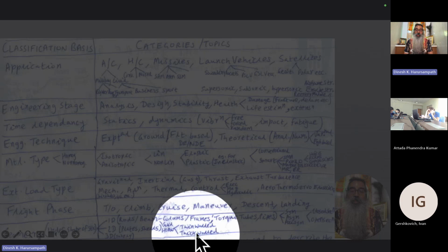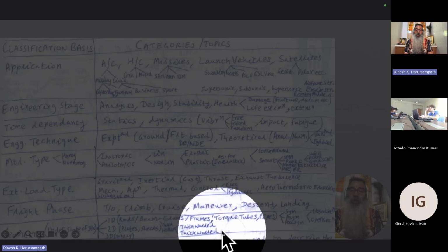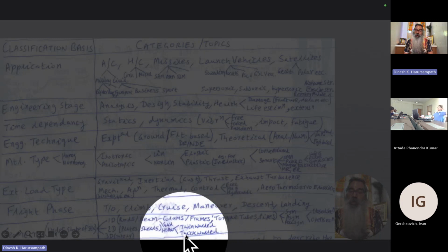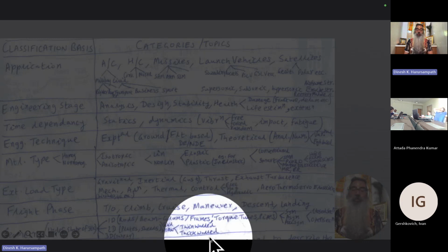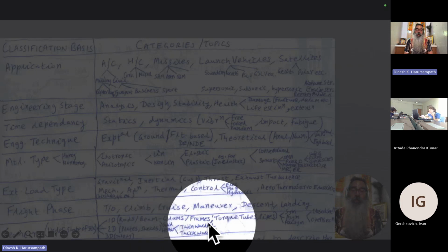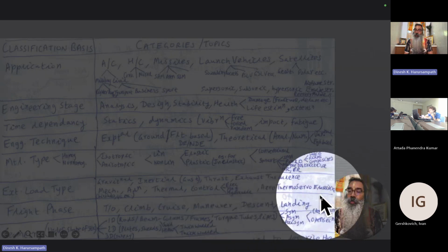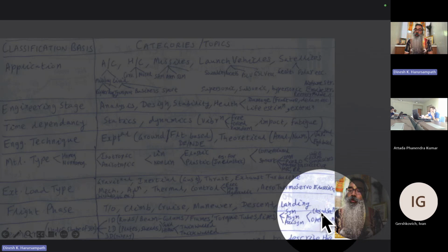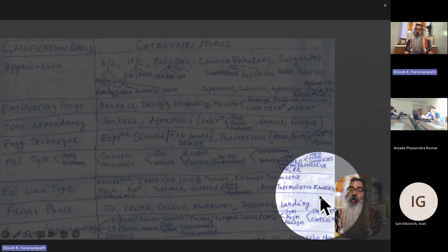So when there's a pressure vessel which is cylindrical in nature, you have stresses along the circumference, which is hoop stress, and along the length of the cylinder, which is longitudinal. And those things you need to be aware of. Depending upon the pressure levels, sometimes we need a thick walled cylinder. But most constructions in flight vehicle structures will be thin walled. And within thin walled, as I already discussed, you could have either a closed section or an open section that you see over here.